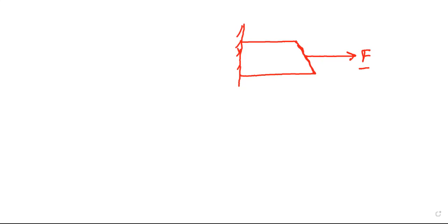stress. You have the cross sectional area, which I am representing in the form of a line. The cross sectional area is A. I should know how much this slanted area is. Let me call this A prime. This slanted area is certainly not equal to the cross-sectional area. So the area of the plane where I have to calculate the stress is A prime.